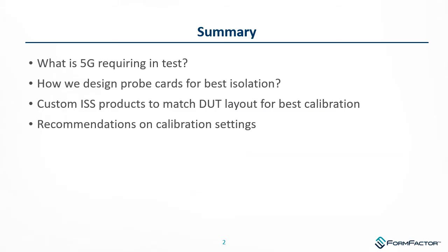This presentation is going to go over some of the specifications for 5G and what they are driving in terms of wafer test specifications. We're also going to describe how we can design probe cards for the best isolation, in particular applying to RF front-end parts such as RF filters.